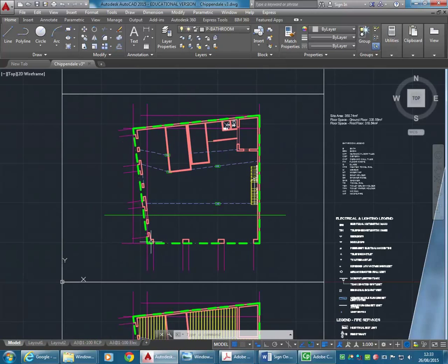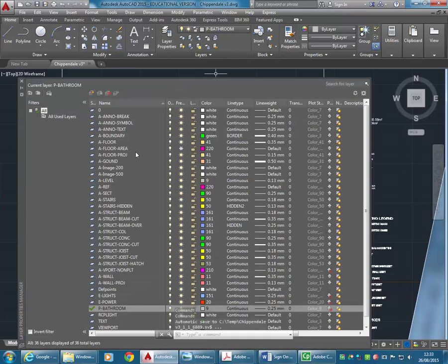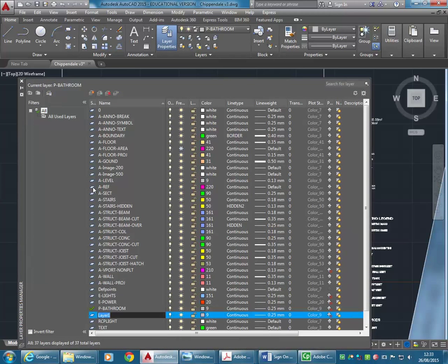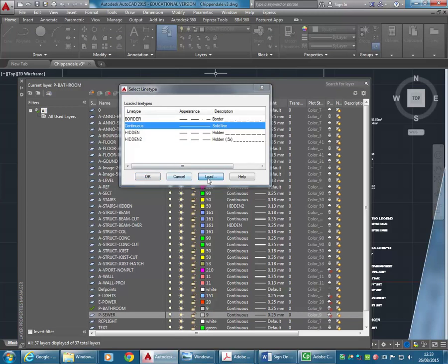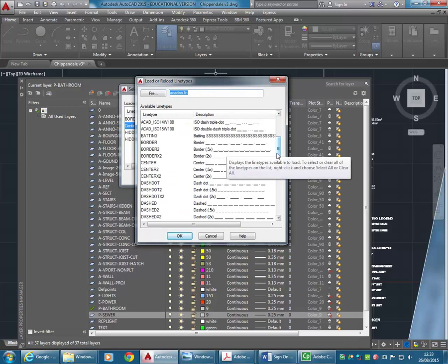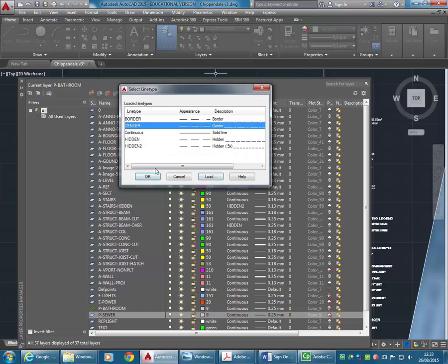So here, this is Kensington Street, I think. So again, let's definitely make a new layer for this. So P sewer. And let's make that have a different line type. So going into here, yep, centre is a good one. Honestly, dashed would probably be fine as well.